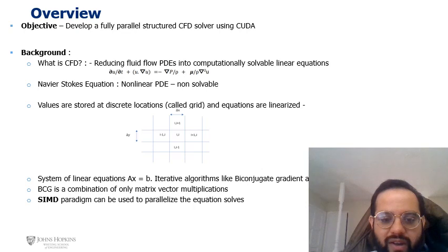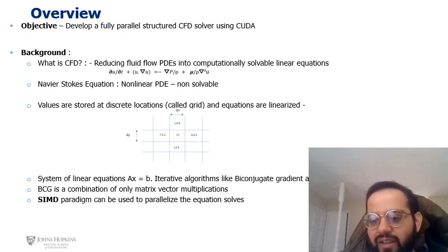And to solve it requires a matrix solve. Of course, this is not solved directly because that is an order n cubed algorithm. There are iterative algorithms available to solve linear equations, which give the result much quicker. One example is the biconjugate gradient method, which I have applied for this project.